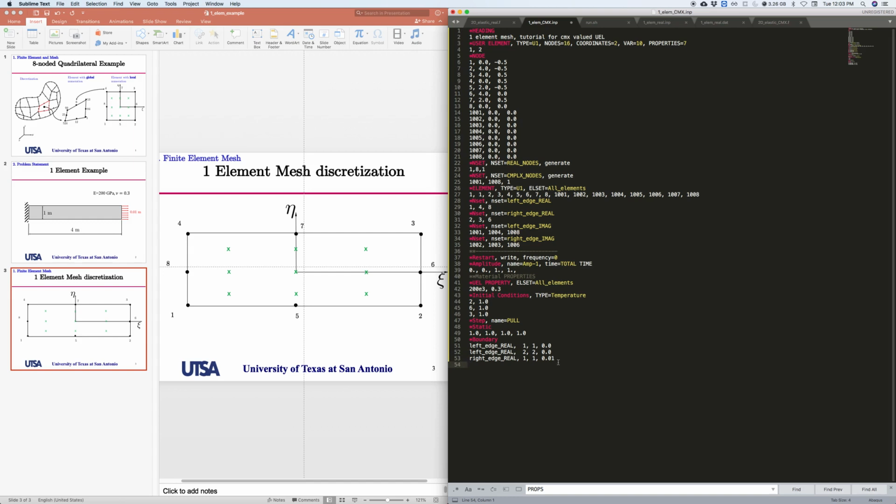And if I apply a boundary condition in the real one, in the imaginary coordinates, I have to also apply the boundary condition but with a value of 0, right? That's in order for the system of equations to solve, right? Because if one is defined in the real, it also has to be defined in the complex. So I'm just gonna borrow these ones, and then I'm just gonna say that it's gonna be imag.